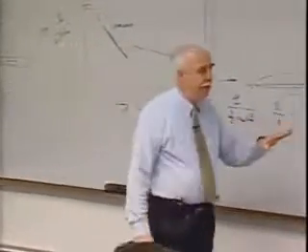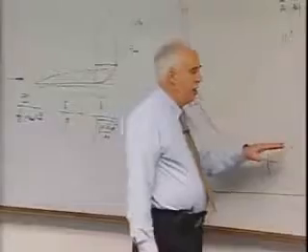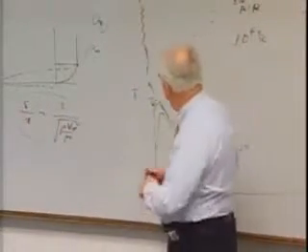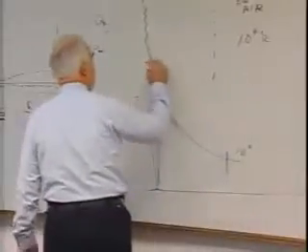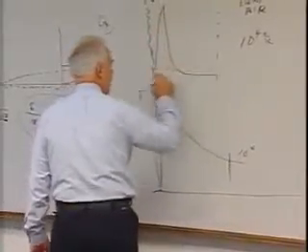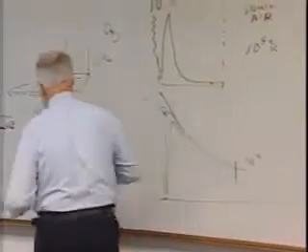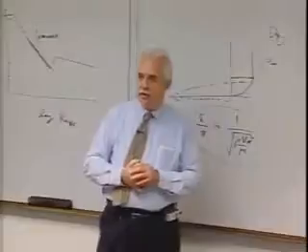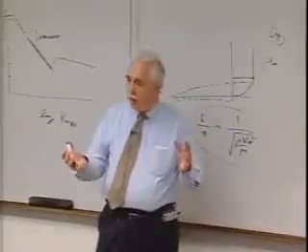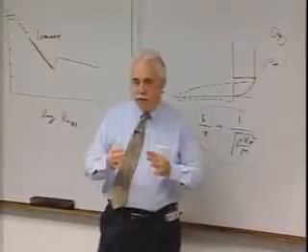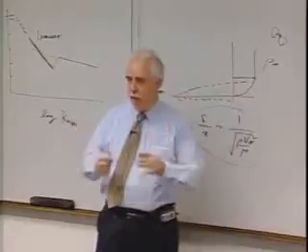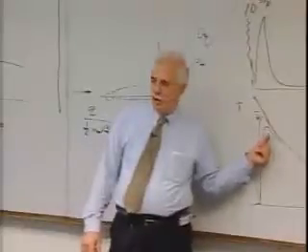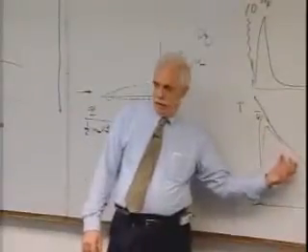It turned out at altitude, the radiation did not agree with this binary scaling that I mentioned, and basically the radiation profile here, as I said, was like two orders of magnitude higher characteristically. But at high altitudes, it just wasn't there. At peak heating, it was. But prior to that, which was a significant heat load, it was not. There were not adequate collisions to excite the radiators before the gas came to equilibrium.